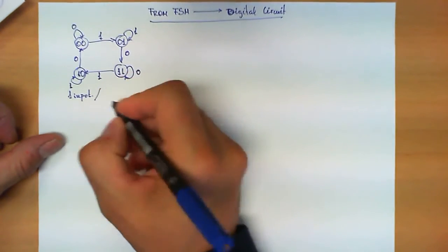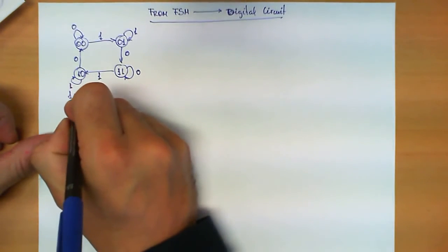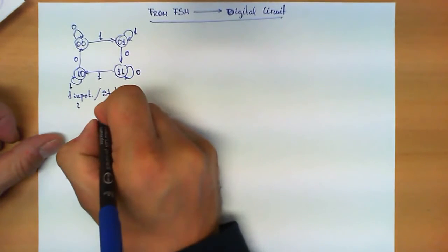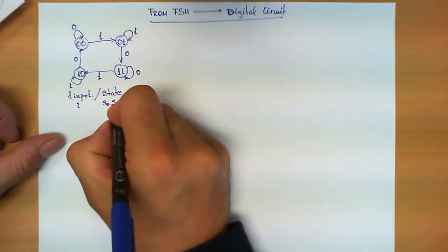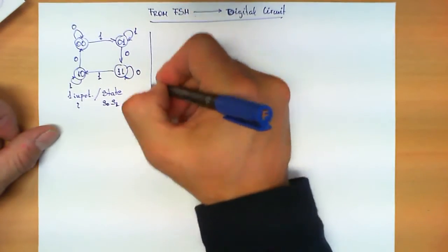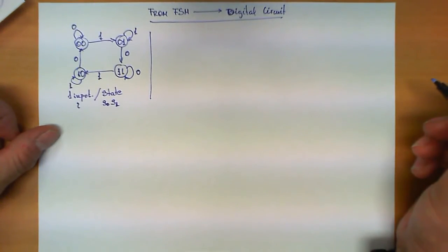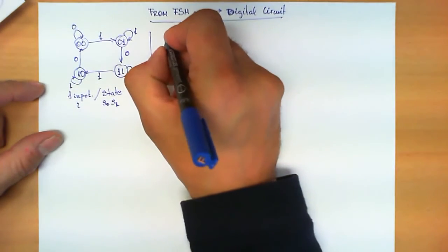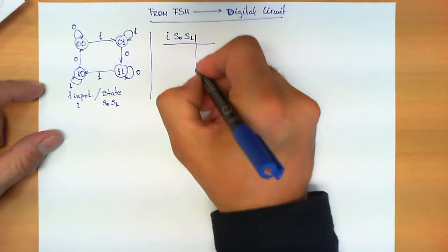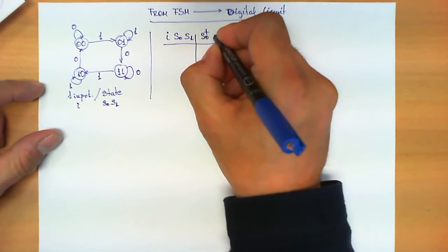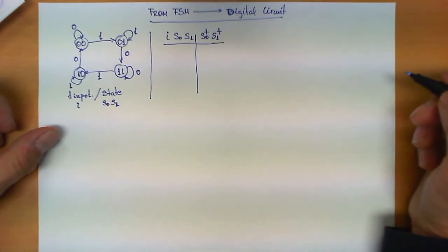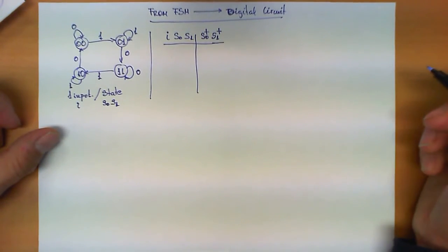Now, aside from 1 input, which we're going to call I, we also have the state of the finite state machine that we're going to represent with 2 bits, S0 and S1. As we can see here, we have 2 bits. Now, from this description, we can derive the truth table in which I, S0, and S1 are used to compute the values S0+ and S1+, denoting the next states to which the machine is making a transition.